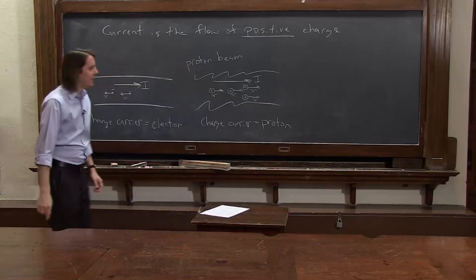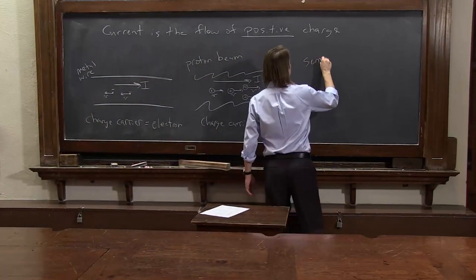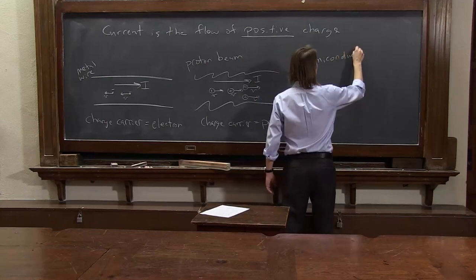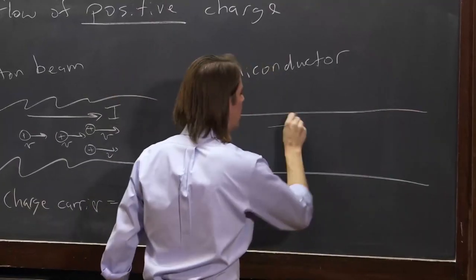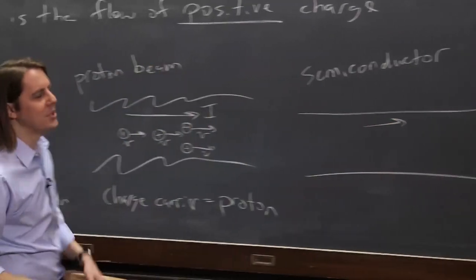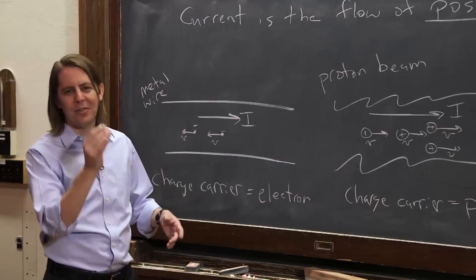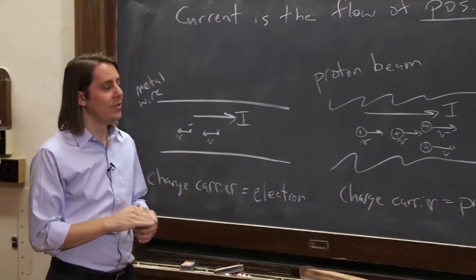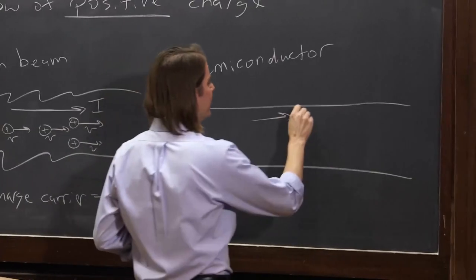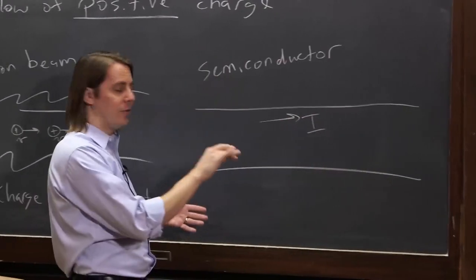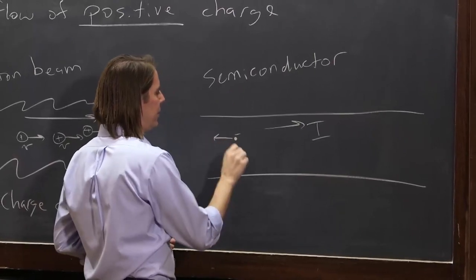All right. It could even get worse. You can have things going in different directions. In a semiconductor, we keep up with electrons and holes. I've mentioned holes, or missing electrons, a few times. In metals, it's not really that important. But in semiconductors, sometimes most of your current can be thought of as holes. So in a semiconductor, if the current goes this way, you can have little electrons flying around, and they'll go this way.